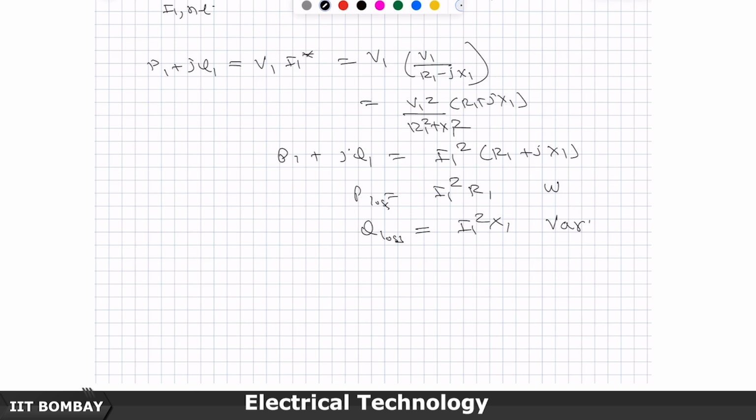Whichever way I do it, I know the 3 phase volt amperes, because I have instrumentation for the line voltages or phase to neutral voltages, and for all 3 currents. So, I know the line to line voltage and the line current, and if I just multiply by root 3, I know the 3 phase apparent power, in volt amperes, being drawn by this.